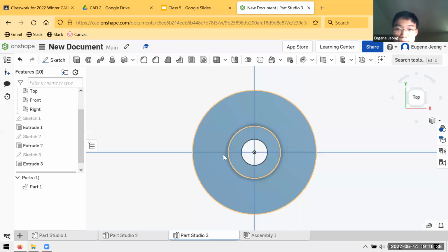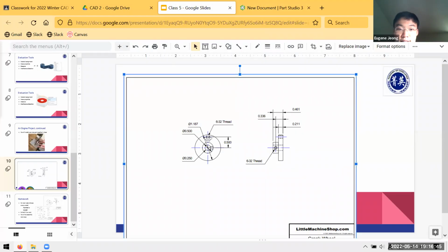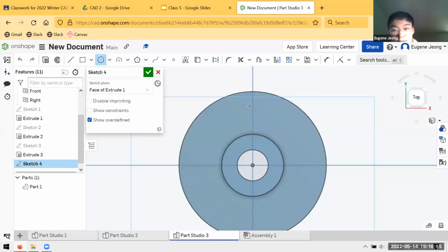So we have one hole going through this surface, so I'll create my sketch on that surface. Looking here, I can see with my line of symmetry that it's going to be 0.5 inches radially away from the center. If I carefully position my mouse, you can see I get that vertical line relation that Onshape will automatically create for me. So I just carefully click right over the middle. Now you can see that it has that relation. I can't drag this left and right.